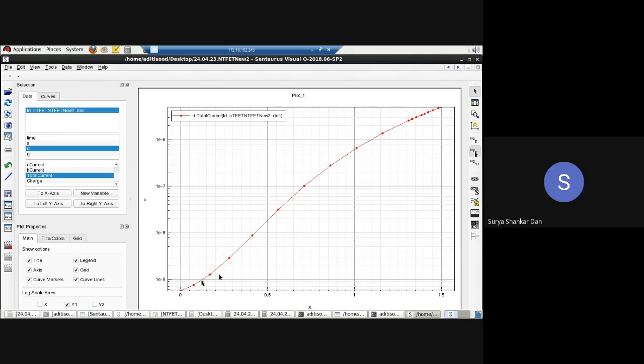In the off current, as I have told you in the class, remember, in the linear scale, you will not see any current below the threshold voltage, right? Now, below threshold voltage, you can see the off current is when you have applied 0 volt to your VG. ठीक है ना? तो VG अब जब 0 है, तब देखो करंट आपका 10 पावर -9 से भी काफी नीचे है, in the order of 10 power -10. Okay, it is lower than 1 nano ampere.